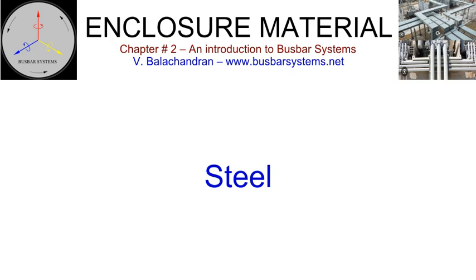Busbar trunkings, installed for the distribution of power in an assembly area or machine shop, are invariably made with steel enclosures. These are characterized by low rated currents and low fault currents, and therefore are not subjected to significant electrodynamic forces. The overall cross-section size is small. Since the weight of the busbar trunking, enclosure plus conductor plus insulating support, is low and is installed indoors, it is not subjected to large mechanical forces.